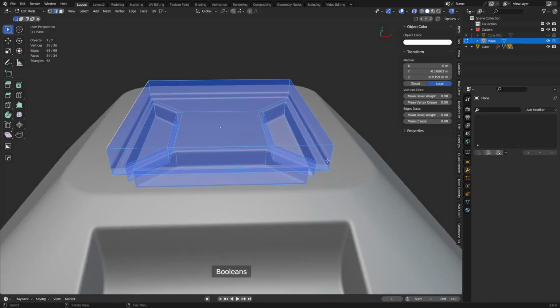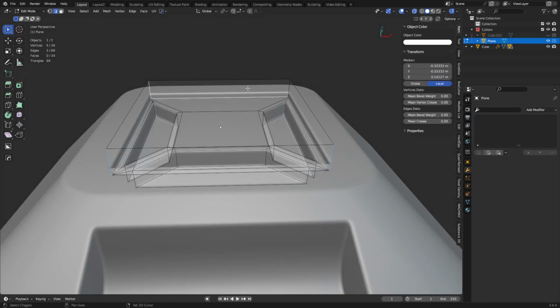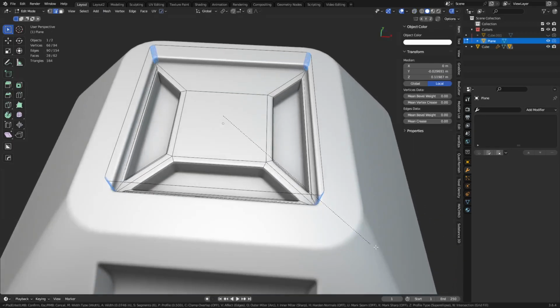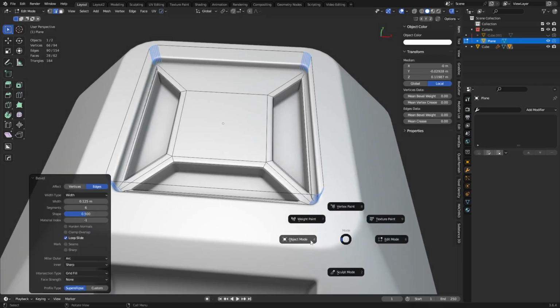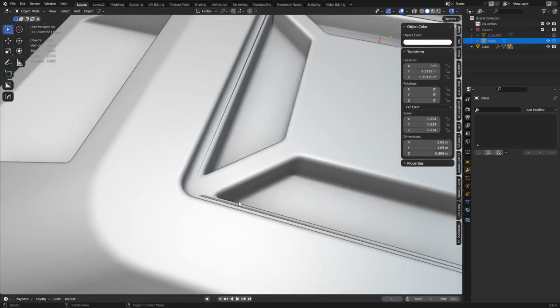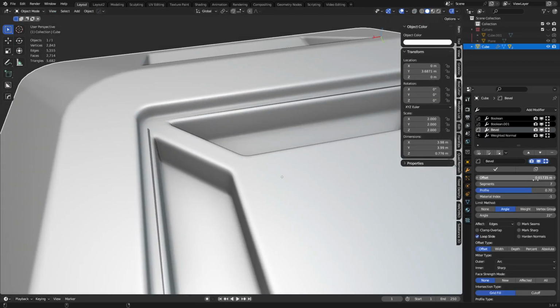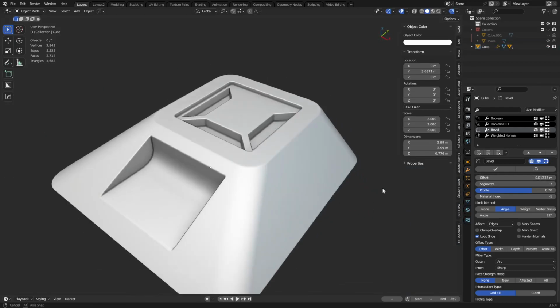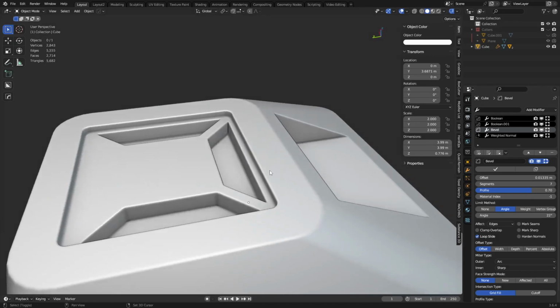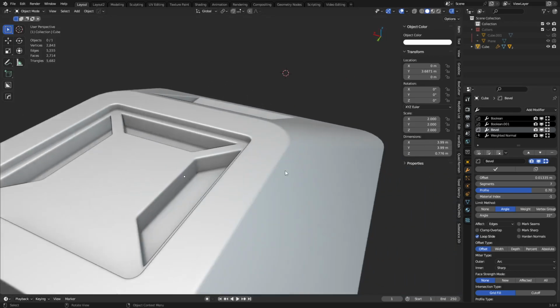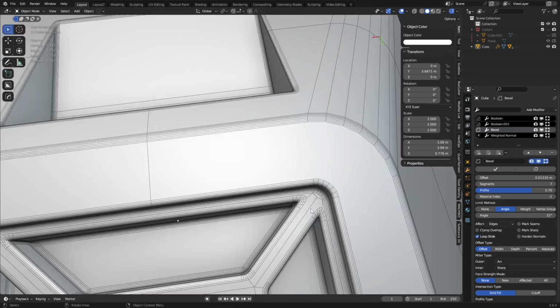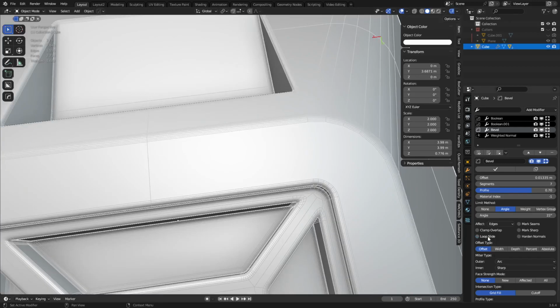Grab the edges here on the corners, perhaps. Maybe give those a little bit of a bevel. All right. See, that bevel's still causing an issue. Bevels on bevels on bevels, but yeah, this is why I do a lot of manual work and don't use these modifiers. Well, I still use them, but a lot of times I have to collapse them, and that's a hit or miss type deal.